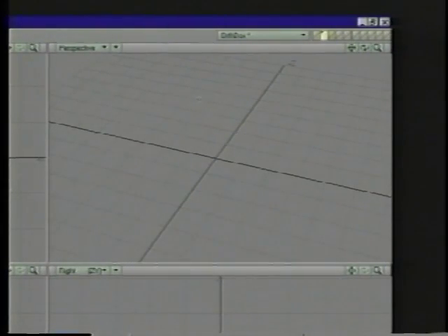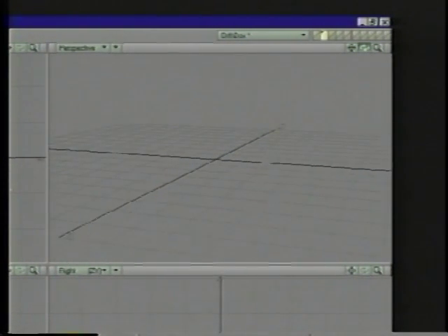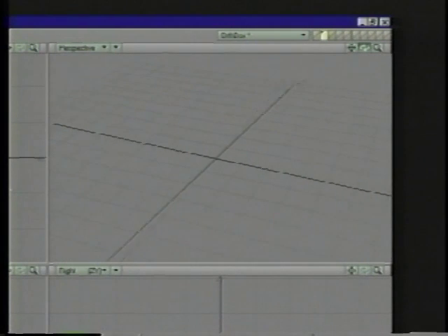So now I've got 4 points created, and I'm going to hit the space bar to drop the tool and create this last point. Okay, so now I've got 4 points in space. You can see I can't see anything over in the perspective view because the points are just reference points for where the geometry gets stitched together, so they're not rendered if they're just points. I can turn points into polygons and make a 1-point polygon if I want to. Lightwave allows that, and we'll cover that a little bit later.